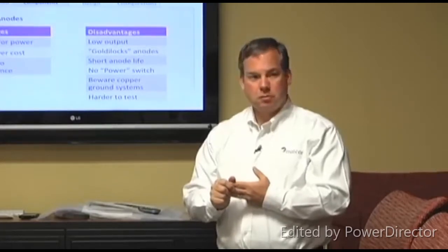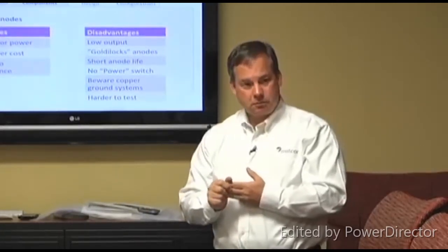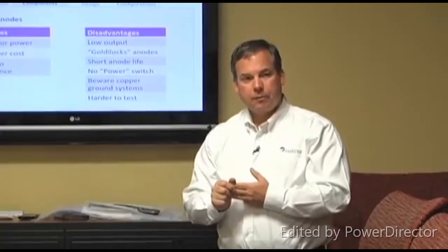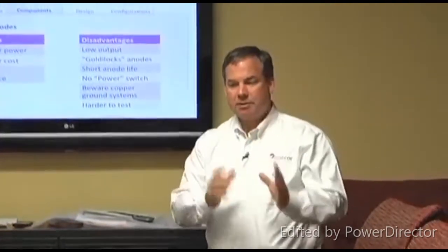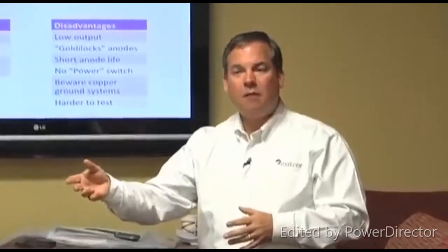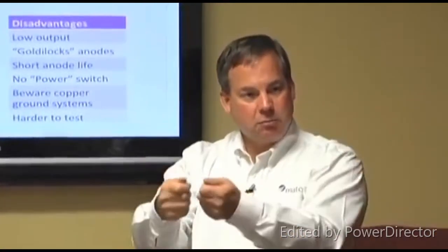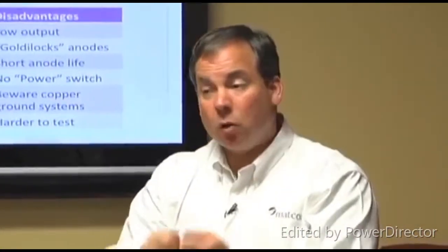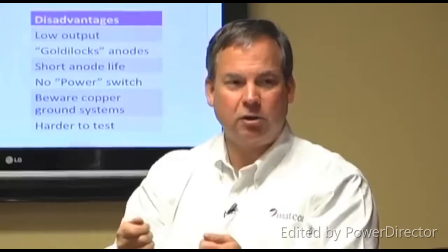But you have to physically connect. They have to be physically connected. Cable from the pipe to that piece of magnesium. Yes, the magnesium has to be connected to the pipe. Often they do it through a test station, so you can actually measure how much current's flowing off it. That's the only really way to know if the anode's still working or not.